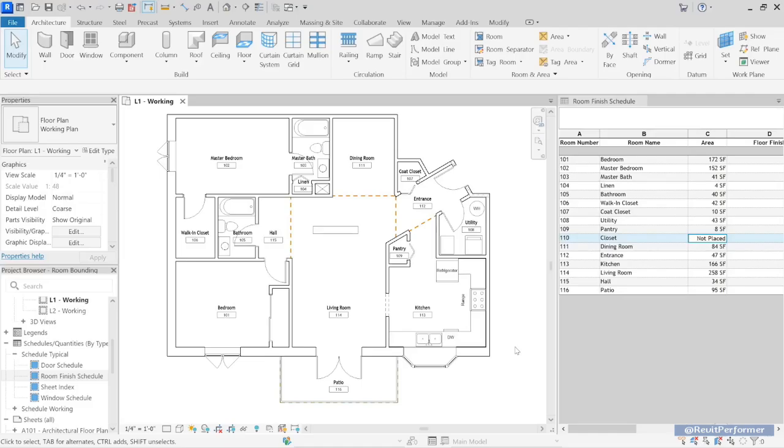So you may be wondering why Revit bothers going through all of this. Why not just delete the room? Why is it giving me all this redundant room and non-placed room and everything? Well, if you consider the fact that rooms are invisible elements to begin with, it might be too easy for you to accidentally delete them. So by adding this extra layer of steps here, it's sort of a fail-safe to prevent you from accidentally making mistakes that otherwise would be too easy to make. So whether you like this mechanism or not, I think it actually is in your best interest, and this is why they designed it this way, so that you don't end up deleting rooms that have a lot of data associated with them accidentally.